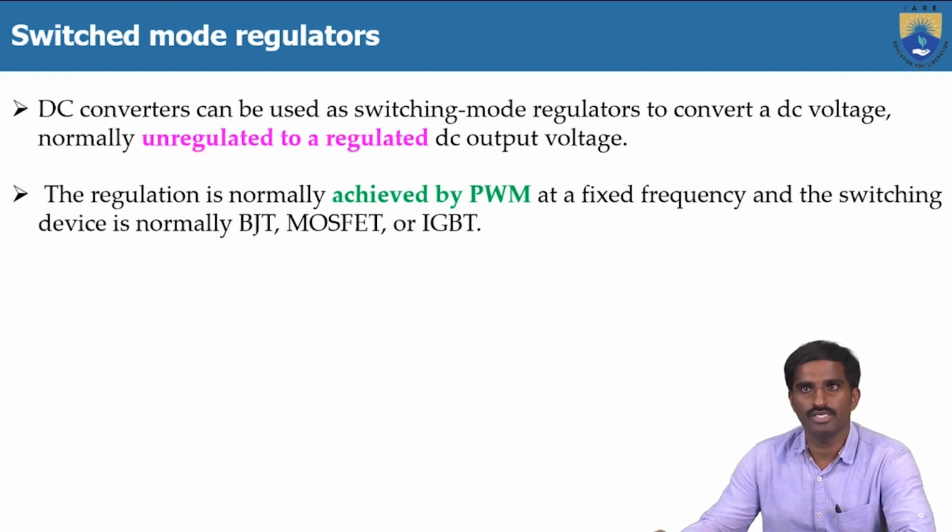Until now, we have discussed different types of DC to DC converters, like the step-up converter, step-down converter, or class A, class B, class C, class D, class E. In all these converters, whether step up or step down, boost, buck-boost or buck converter, the chopper switch or semiconductor switch that we considered is a thyristor.